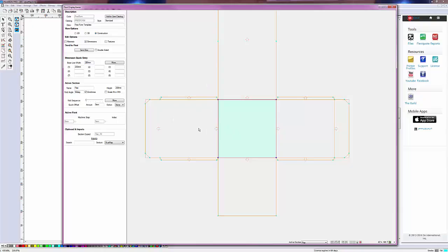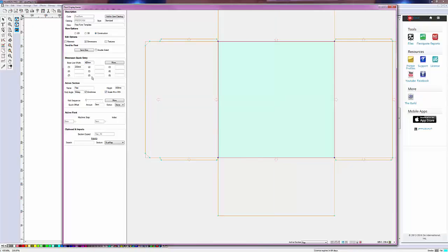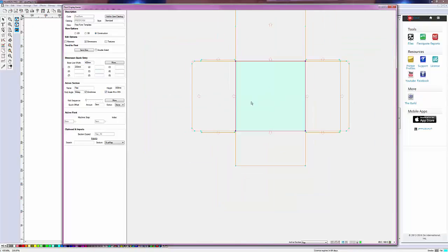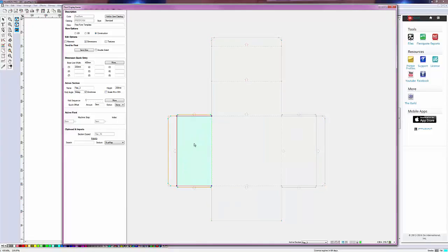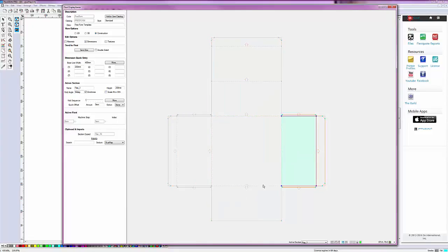So let's start by making this base section remain square. We do this by setting this constant aspect ratio flag. If we do that and double the size, then we find that these sections are no longer square. So I need to set the flags on those as well. I must go back to 200, however, because otherwise they'll be locked as being 2:1 aspect ratio rather than as 1:1.